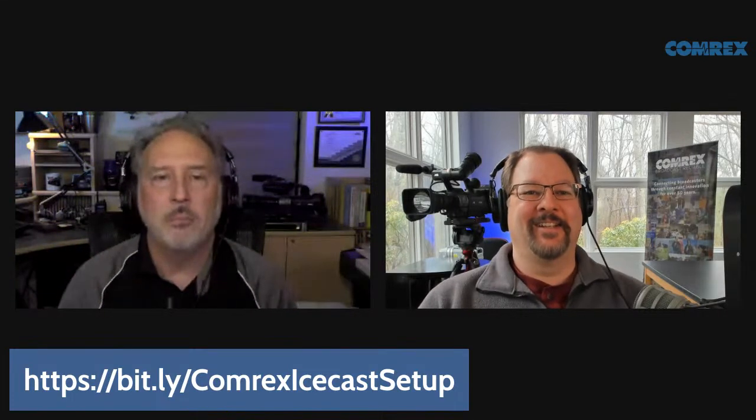Okay, so let's say that I'm a Comrex customer. I want to be able to feed my streaming server. I've got a Bricklink or an Access that I can use for that. How long would it take me to set that up if I were to call E4 and get the expert tutelage on it? Yeah, it's really only a couple of minutes. You would need to get the information from the streaming service. There are certain very particular things that are, again, a bit different from what you do if you're connecting with another Comrex device. There's a source and a mount point, and these are really just pieces of information that would be communicated by the streaming service that match up with what they're going to expect from you.